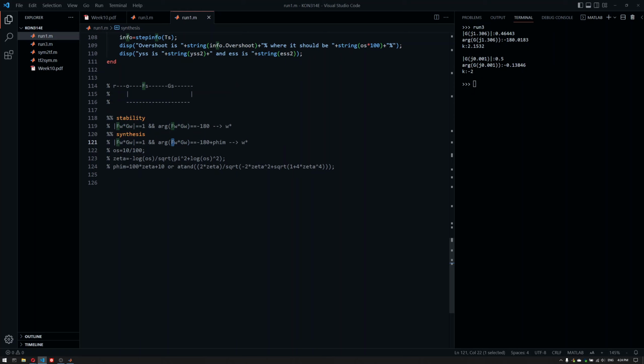If it's less than or equal to 10, you can add 10, then subtract 10, it will correspond to the same thing. Then you can go ahead and read the value from here, use that frequency and the gain value to come up with the lag controller. You know how to handle the p-type controller. For the lead controller, it will be beta instead of alpha, and there are some other assumptions, but it is quite similar. You can use your lecture notes to study that part.